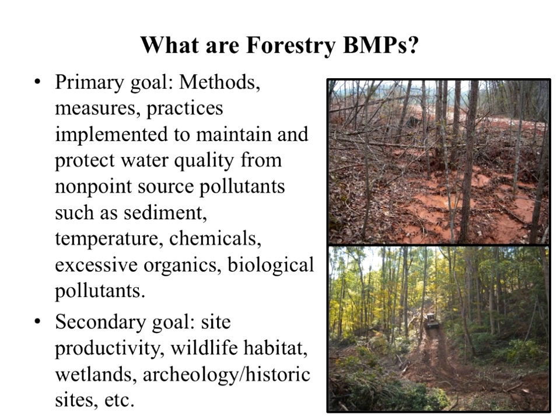Now, in this particular case, I'd like to emphasize this, because this is a good example of where pre-harvest planning might have been a BMP that we could have used to improve the skid trail, before we had to deal with the problem in the end. And the streamside management zone is a good example of a BMP that actually is helping us to prevent a water quality problem that was due to another situation where perhaps additional BMPs might have been used. So I'd like you to keep that in mind, because SMZs are a good way of dealing with a problem that might occur, and pre-harvest planning is a good method of dealing with it ahead of time. Some people consider those to be two of the most important BMPs. And again, they're all important.